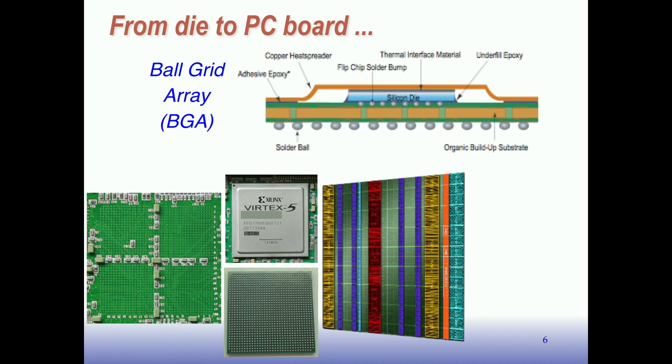So what you see here is connections between the silicon die down to the substrate. Then the substrate has multiple layers of wiring, and it can spread out those signals and make connections to this set of balls here. It's epoxied down. Then there's this copper heat spreader that's put on top, and it's painted or coated with something. It looks silver there. In some applications, there'll be a heat sink put right on top to additionally help put the heat out.